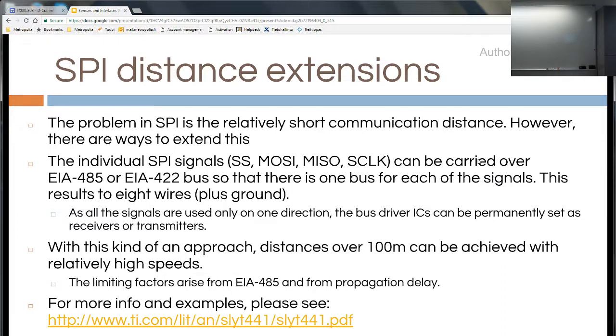Well, the biggest issue is the signal attenuation, and of course the capacitance kills the signal form. And then when you go really long lines, with high speed you may actually have some issue with the return. So master out is always okay with the clock, since those are synchronized, but you may actually end up losing the phase shift with very long lines, but that would mean kilometers of line and very high speed.